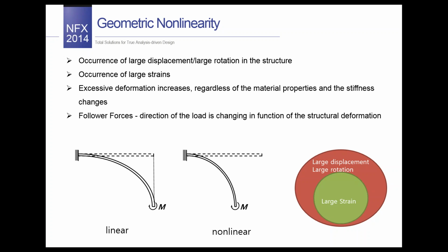Small strain problems are associated with small or large rotations, and problems in which small rotations occur include struts, shells, arches deflected by transverse load, for example, clamped circular plates under transverse point loads, and some shallow spherical caps.